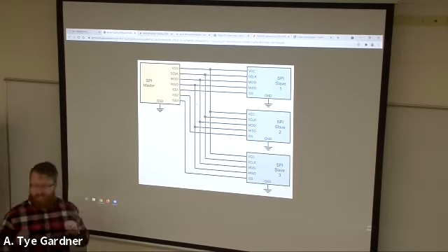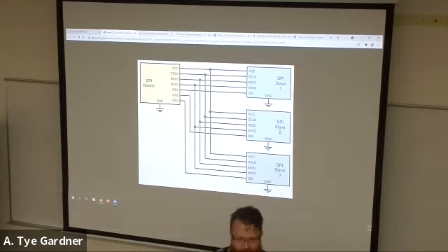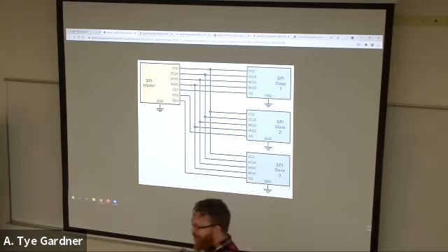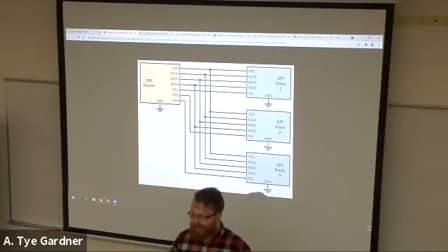You can do a SPI in like 3 states if you're really ambitious. I don't recommend doing that many. You guys are actually very lucky in this one because you are only sending data to the DAC. So the labs I built are very simple, right? Had you build a receiver, then I built a transmitter that you had to know how it worked in order to get the receiver. This one, we're building a synchronous communication that only transmits. And then the next one, I2C, is transmit and receive in a serial communication. So I'm slowly building you guys up, so there's no big cascading surprise of difficulty. Unless you're super behind, which hopefully we're avoiding this time.